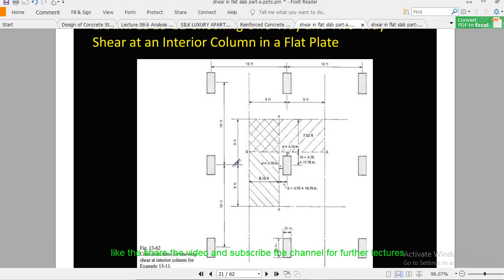You see 9 plus 9, because from the center of the column it is 9 feet on this side and 9 feet on that side. So 18 by 18 feet will be the tributary area for punching shear, subtracting the critical section area. We have to find out that area and subtract it.